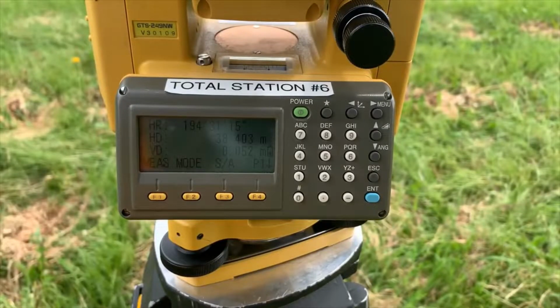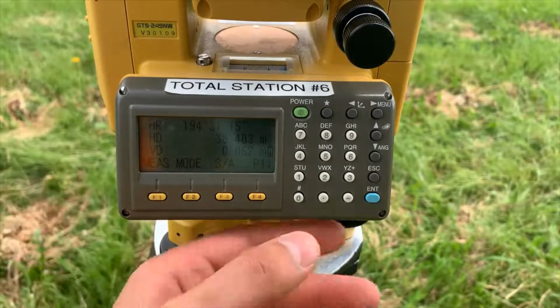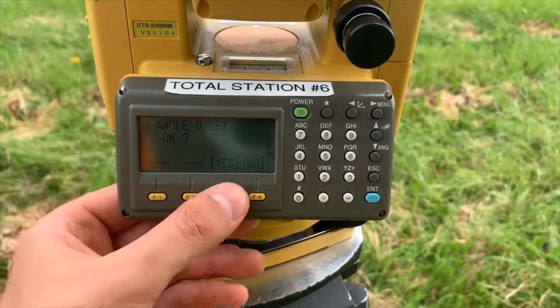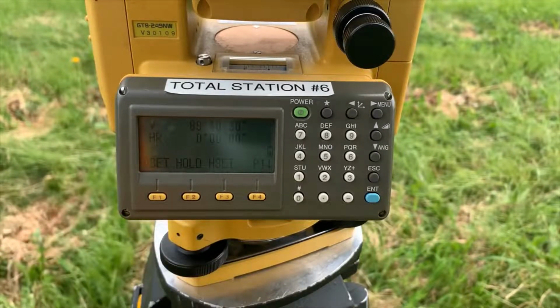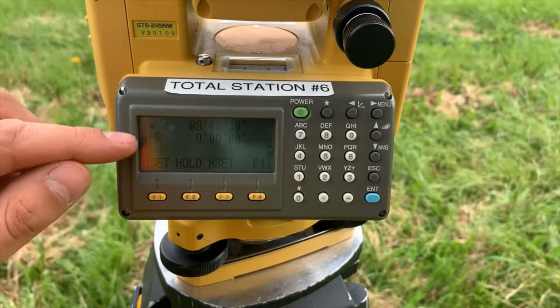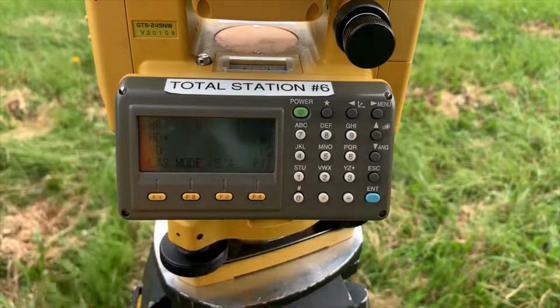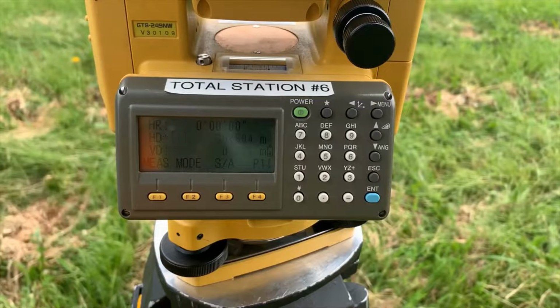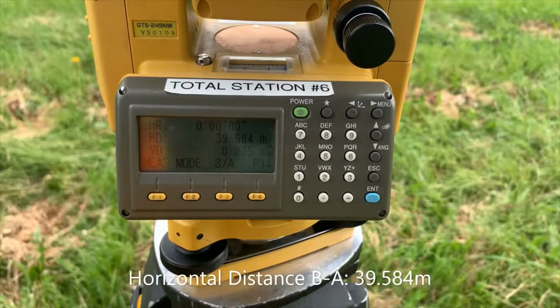So now we've set up our total station over B6, and I've sighted over our prism set up over A6. And so again, we're going to go to angle, and zero set on that prism. So our horizontal rotation is 0, and now we'll take a distance measurement and collect our horizontal distance, which is 39.584 meters.